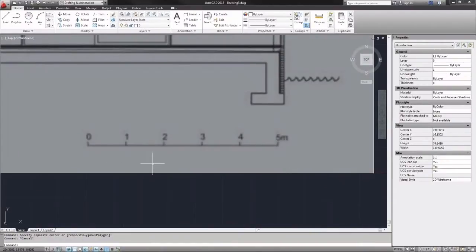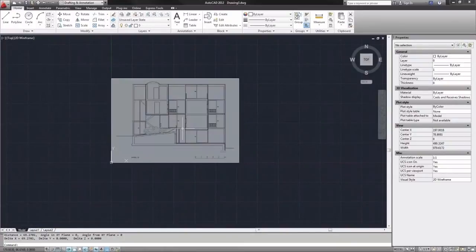So next we will try to figure out how big this image is. We can use this scale here in the bottom of the image. We can go ahead and measure it, typing distance, and click one end of the scale, and then click near the other end of the scale, and that says 69.2 millimeters. So that is very small in comparison to what we actually want, which is 5 meters or 5,000 millimeters. So rather than doing the math and multiplying this image by a specific number, we can scale by reference.